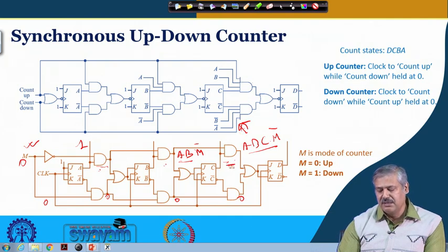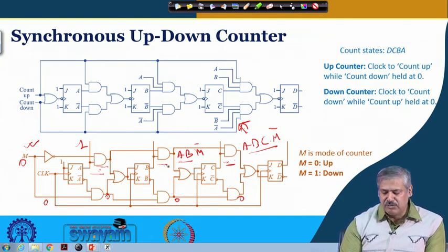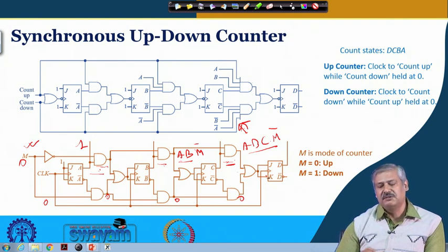In this arrangement, we are having only 2 input AND gates, but the thing is that there is an accumulation of delay before clocking, of course, not after clocking. So a flip flop has changed, and after that the delayed value will make the appropriate clocking available to the next flip flop.